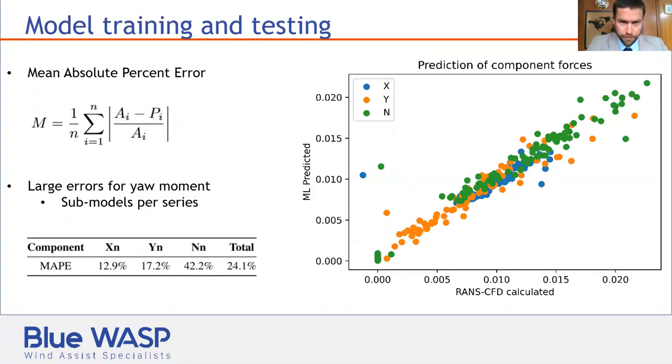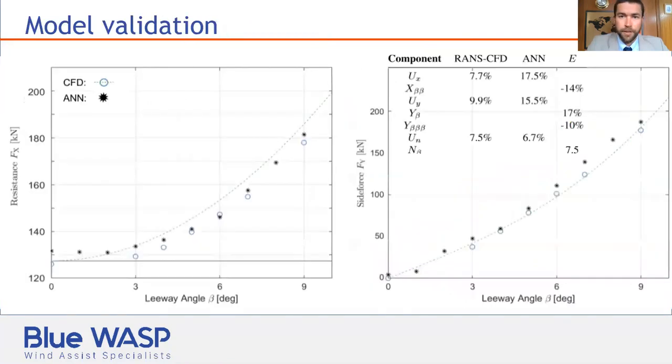In general, the uncertainties are approximately commensurate with the underlying validation level for the RANS data, and next to that, the comparison error. So if you look here, this is an example of a validation case. We have the hull number 1 from the series, so that's simply the parent hull. Blue is the CFD result, and black is the neural network result. And then here there are some maneuvering coefficients, as typically done for ship maneuvering, with corresponding uncertainties for the data, so not for the coefficient.